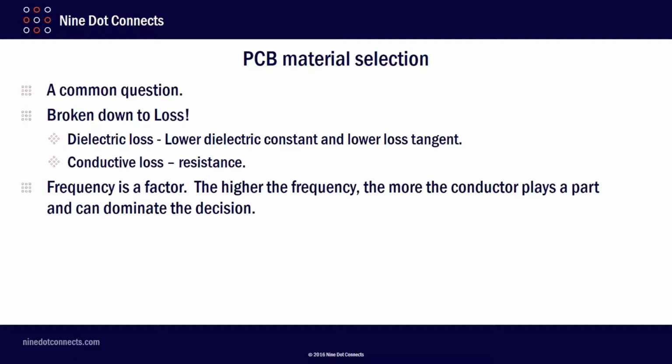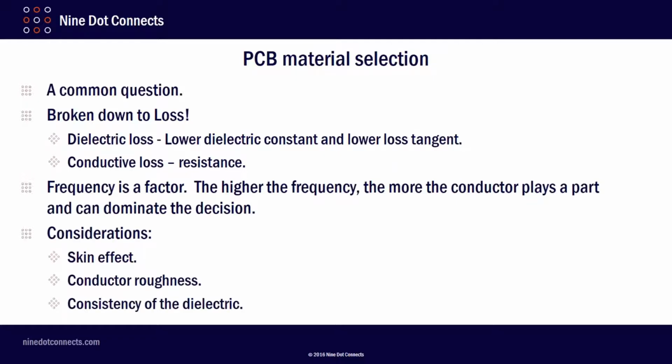Frequency is a factor. The higher the frequency, the more the conductor plays a part and can even dominate this decision. In that, I want you to consider skin effect, conductor roughness, and then consistency of the dielectric.